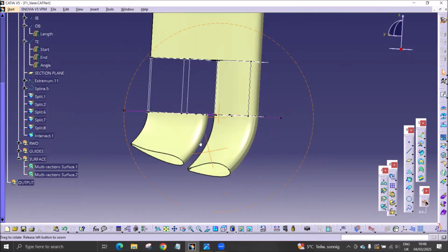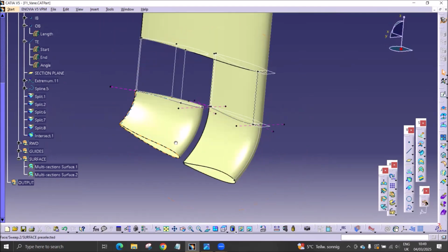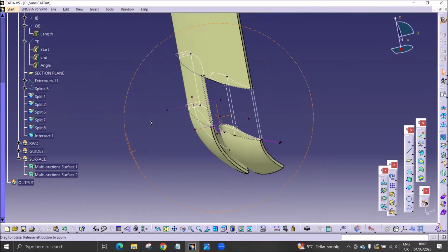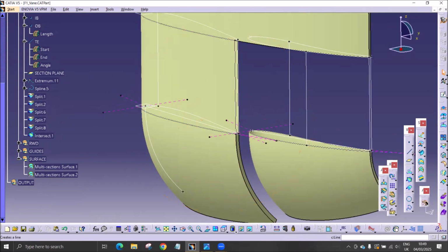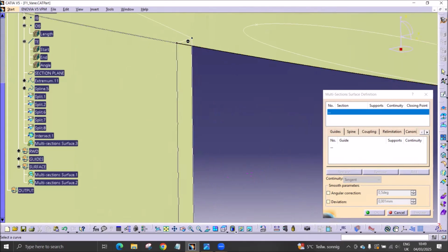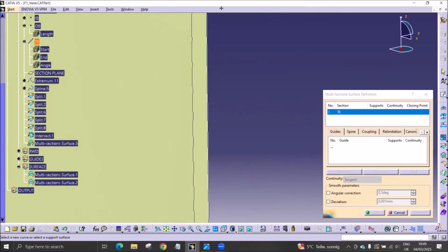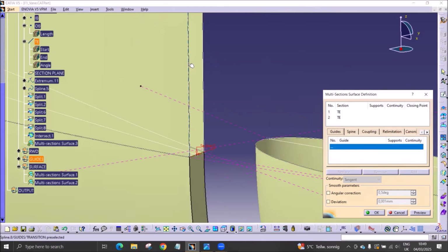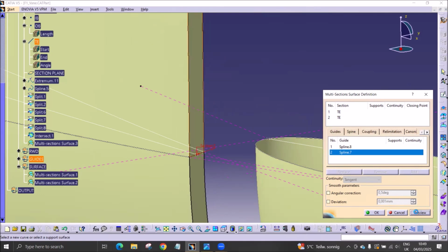Okay, so we already have two surfaces. We are still missing the trailing edge. Also, the trailing edge will be built with a multi-section, just in case we want to have profiles in different positions later, and the trailing edge won't be as straight as it is right now. It can also be curved in any direction, so this is a super flexible model that we are creating here.